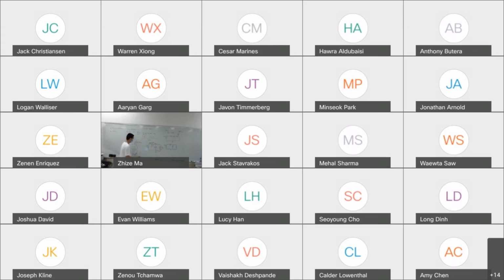There are 4 pins on your DMM. 1 pin is for voltage, which you already use. The other 2 pins are for current, and you will use one of them. The one marked amp is for measuring large current. That one has a larger range, but less accuracy.